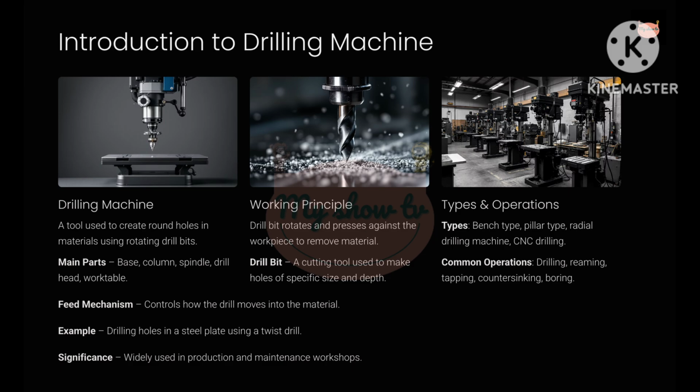The working principle is simple. The rotating drill bit presses into the material, gradually removing it to form a hole. Common operations are drilling, to make holes. Reaming, to finish holes. Tapping, to make internal threads. Countersinking, to prepare holes for flathead screws. Drilling machines come in different types like bench type, pillar type, or radial type. For example, using a twist drill to create holes in a steel plate. These machines are essential for mass production and fabrication, especially for assembly-based industries.